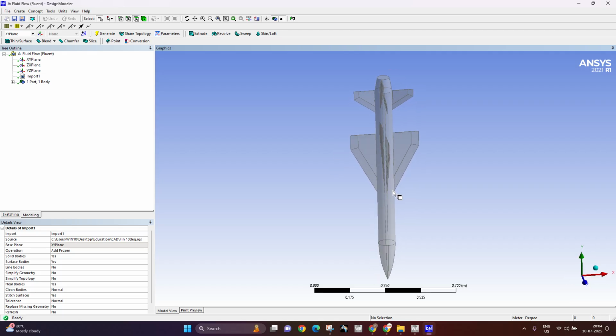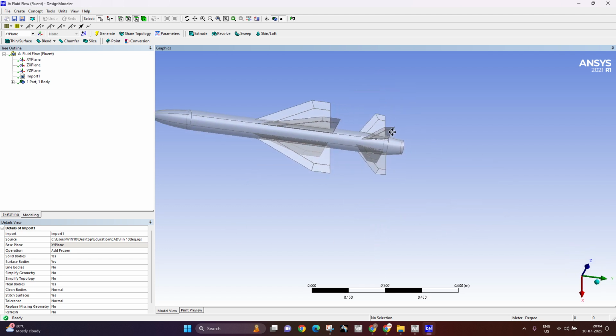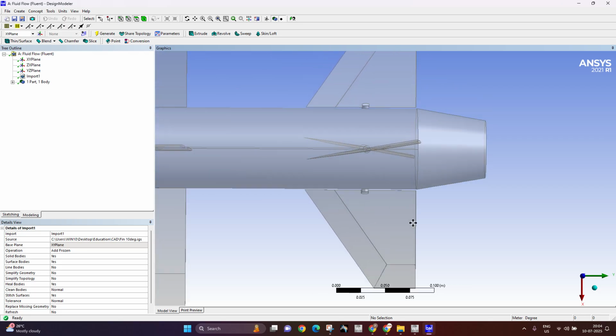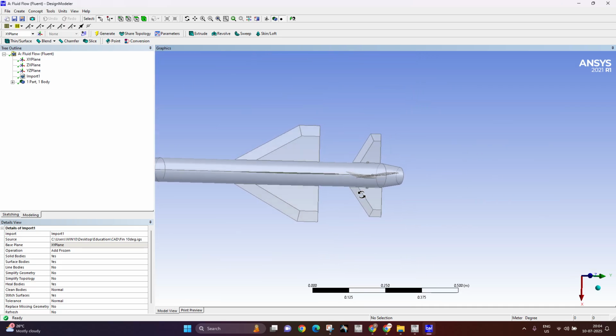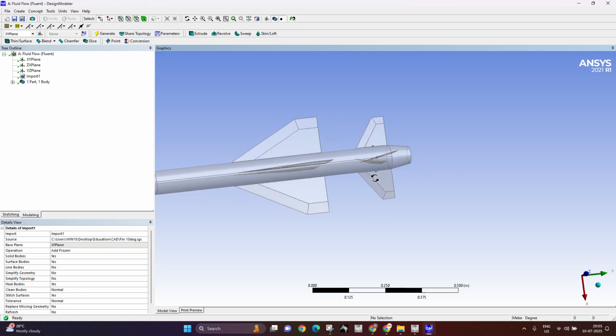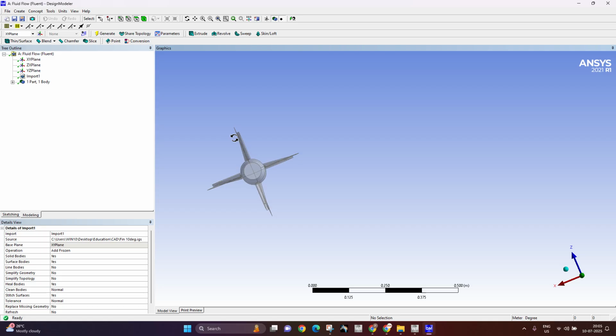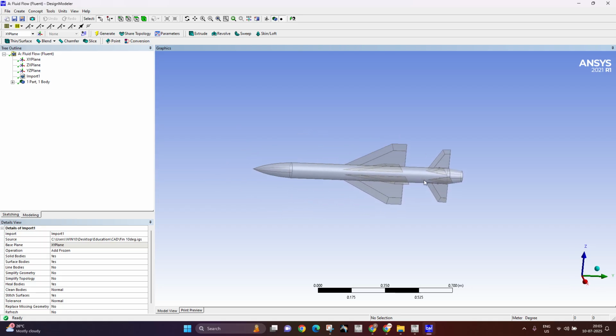The thing is, we will be performing external airflow dynamics upon this missile, basically to find out how the turbulence or the vortices have been created. Now, the main intention of this analysis is because you can see these fins, right? The missile fin has an increment of 10 degrees. The missile actually rotates when it is moving. You need the control surfaces to act accordingly, right? So it is at 10 degrees. So we will check out how the overall characteristics of it would be like.